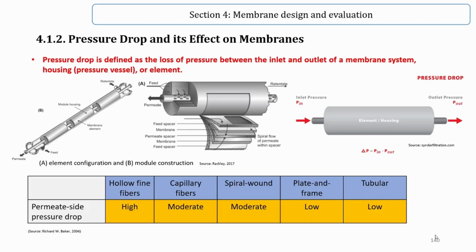When a pressure drop exceeds the normally reported value, it indicates that physical plugging or scaling of the membrane is taking place. An excessive pressure drop can cause the membrane and/or materials of construction to move and sometimes break, eventually resulting in a complete failure of the membrane.